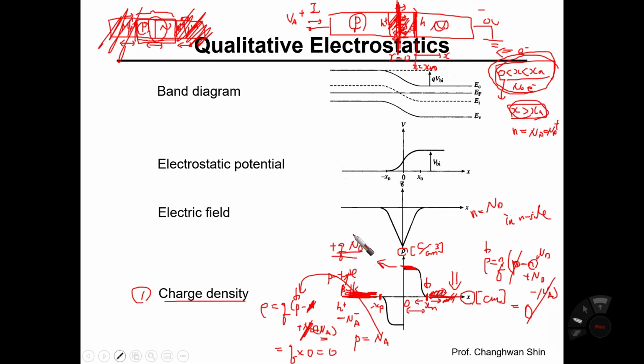If there are no specific conditions on how the dopant atoms are distributed in the N side, the basic assumption is that donors are uniformly distributed in the N side material. Therefore, the doping profile of the N-type material is uniform. So we can simply claim that Q times N sub D is the charge density.